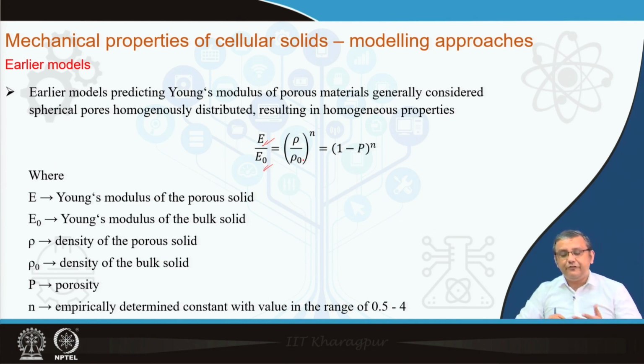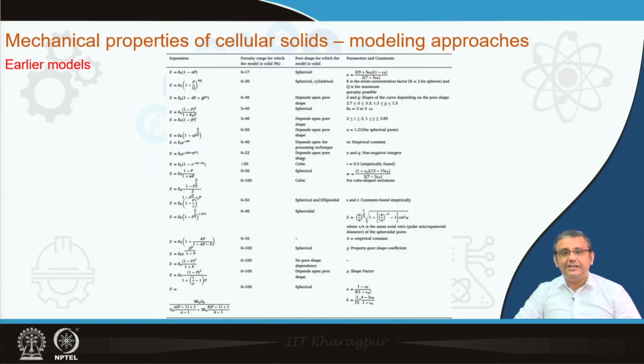And these expressions are very simple. I mean, there are several expressions that have been proposed. As you can see over here, there are many such expressions. Typical expressions for Young's moduli are being shown over here, but many other expressions have also been proposed to predict the dependence of the Young's modulus on the porosity of the material. Again, Young's modulus has been studied very often for porous materials, because it is structure sensitive, and any deviation in the pore size and the pore morphology will actually affect the Young's modulus of the material.